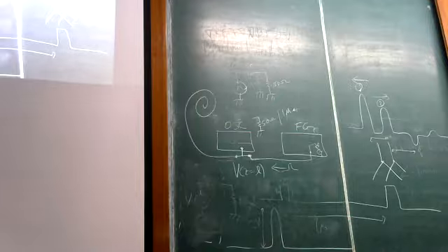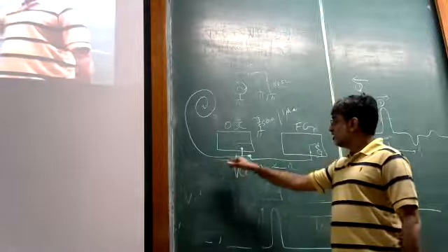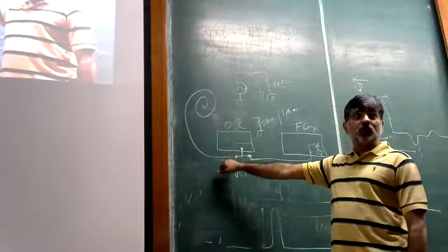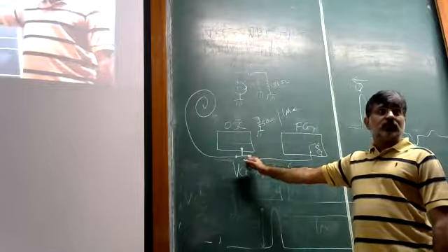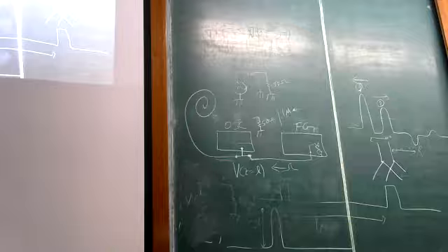But why is the sign inverted? Louder. There is a 50 that sees a 25. Does that make sense? For the wave which is returning back, the condition is that the source impedance is 50 ohms and the load impedance is 25 ohms, which is smaller than 50 ohms.